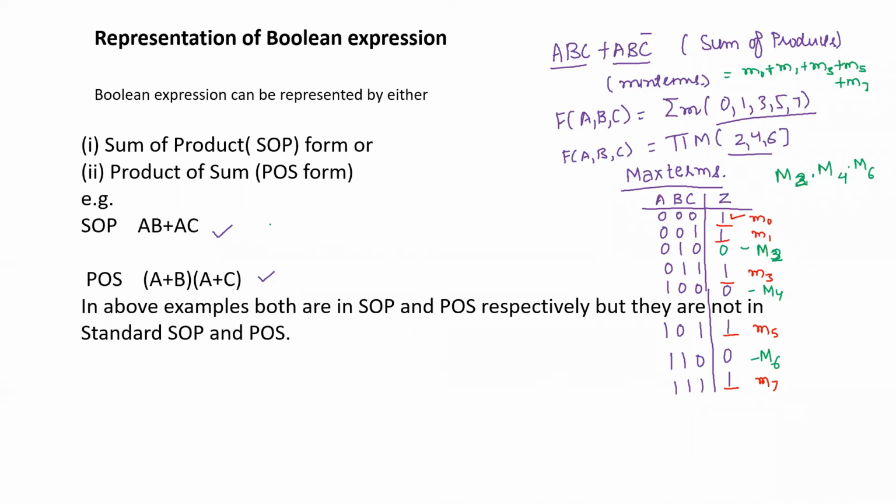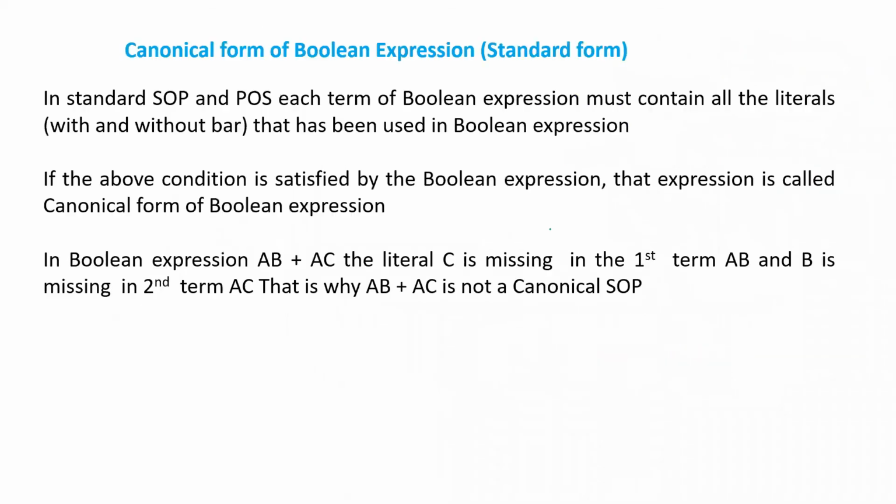And this is another way by which product of sums can be represented. So if you are writing it like this, A, B, C, it will become A bar plus B bar plus C bar and all. So both ways are equally acceptable, but we normally prefer minterms for which output is 1 and we solve it. And the technique which we have discussed till now is your Boolean algebra minimization technique.